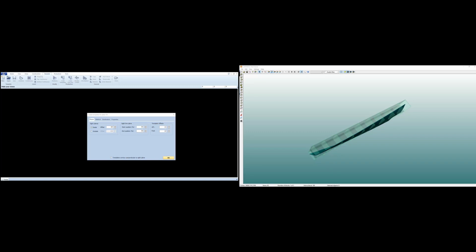In the first tab of this panel, we can manipulate the side planes, the sideline plane, and the offsets of the first and the last template. As you can see in the hull viewer, when this panel starts, the system uses all defaults and it calculates automatically the default templates for this shell plate. So what you see in the hull viewer is only a preview. Now the templates haven't been created. By having this preview, whenever you change something, you see what happens, how they will look like.